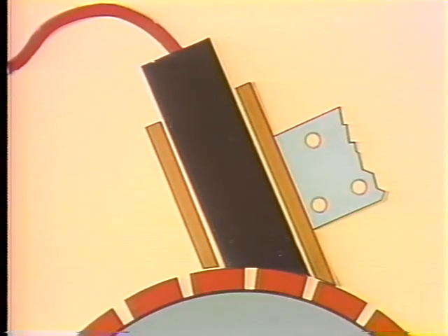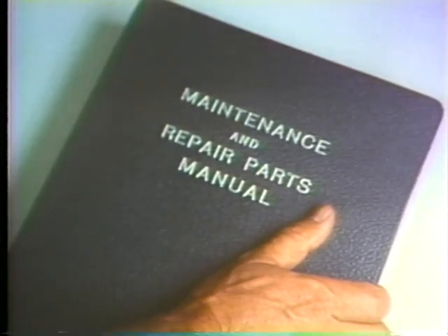Too close to the commutator surface isn't any good either. For one thing, it increases the danger of arcing from the commutator to the rigging. The brush holder's usually made of metal, so it's a better conductor than a carbon brush, and current is always going to follow the easiest path it can find. Check the motor's manual to find out exactly what the distance should be and set it accordingly. If the information's not available, a good rule of thumb is to set it between 1/16 and 3/16 of an inch from the surface. Using the metric system, it would be 1.6 to 4.8 millimeters from the surface.